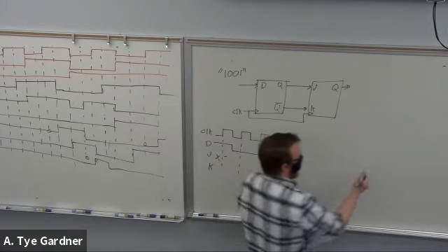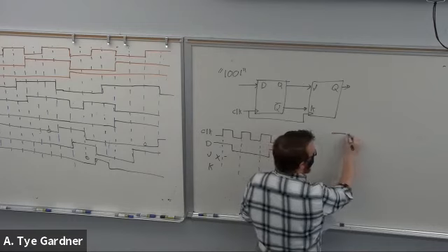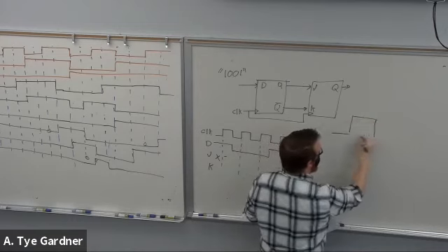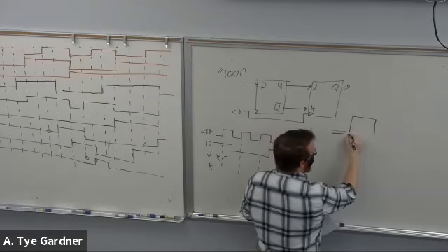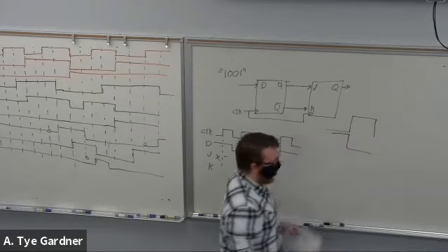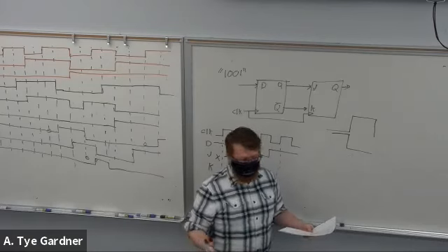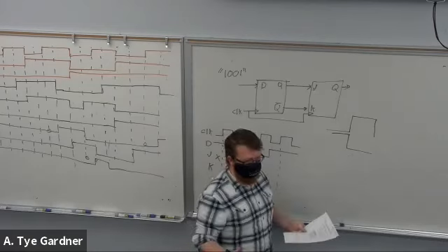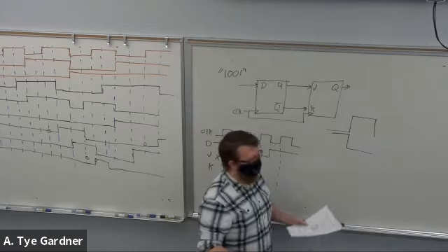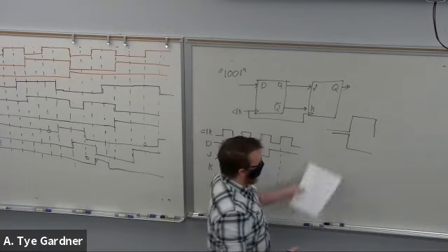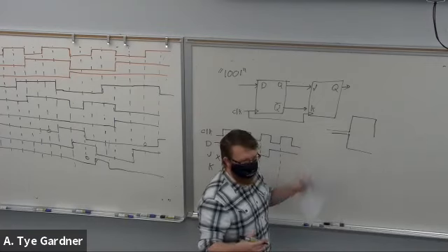The reason being, let's say I have a clock here, and at the same time I'm going from 1 to 0. There's kind of this question of, am I clocking in a 1 or a 0? In real life, if you have real devices, we have the setup time requirement because it's unclear.